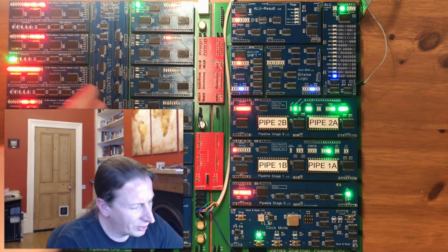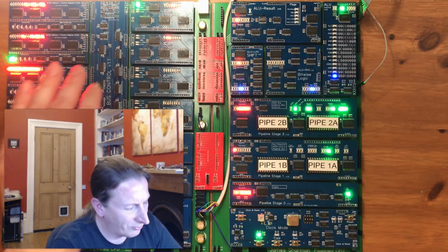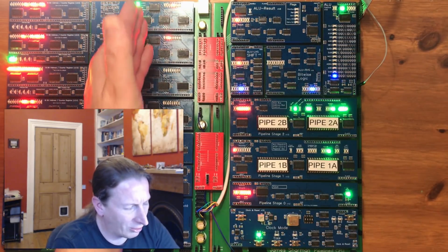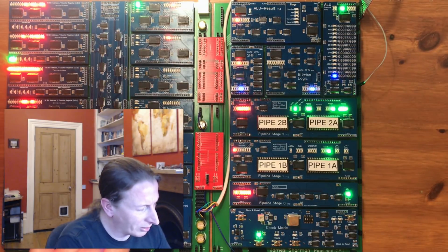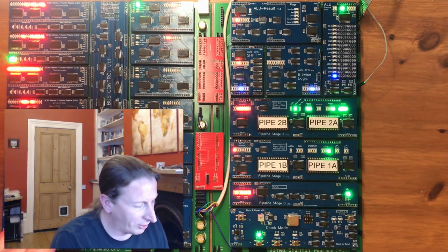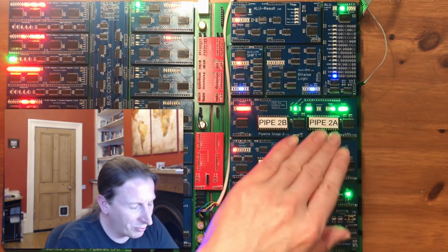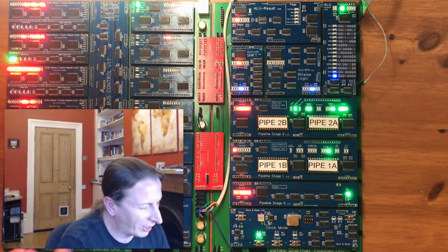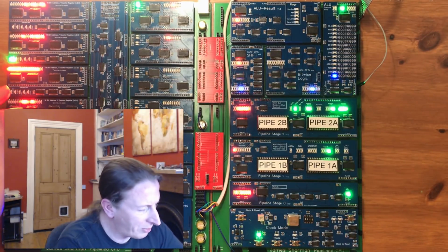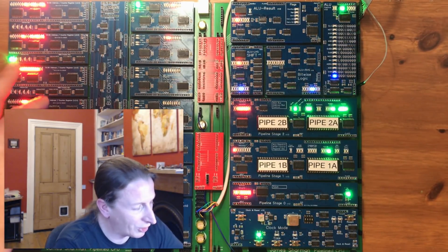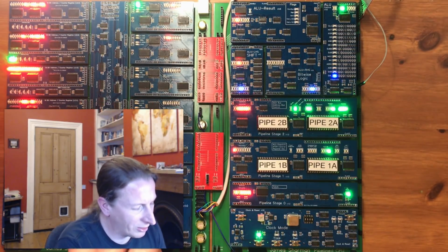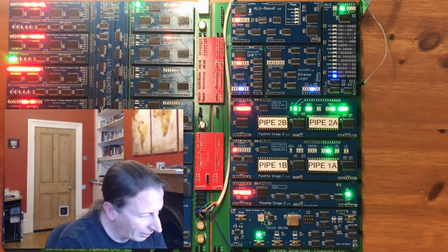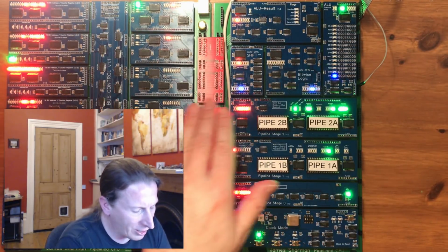So I could set any of the 16-bit registers for any of the combinations of 8-bit register I wanted to, and that would allow me to do away with the need for the transfer register. Now I'd need some custom ALU operations for getting data back out, because if I pushed the 16-bit register onto LHS and RHS, that would mean that I had hardwired the side of the ALU it was going into.